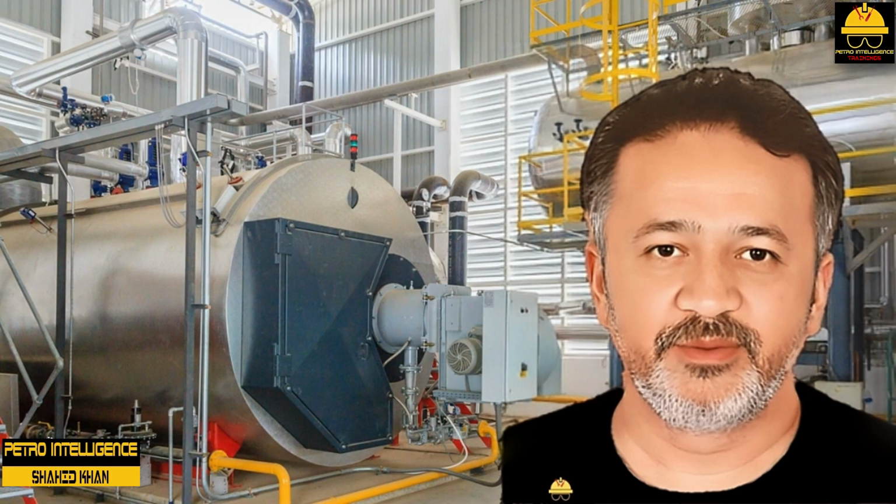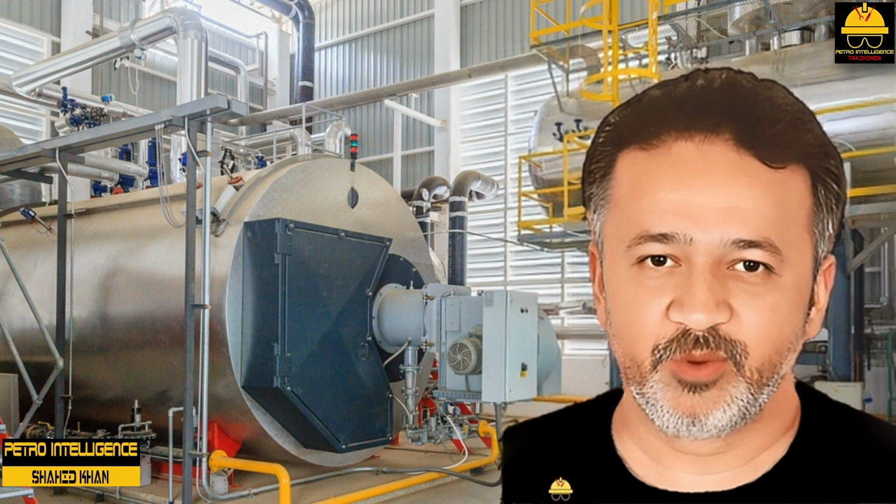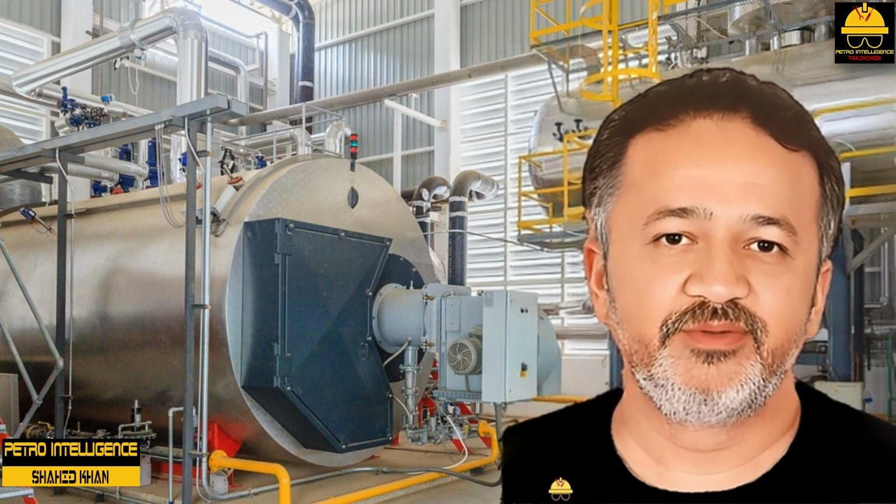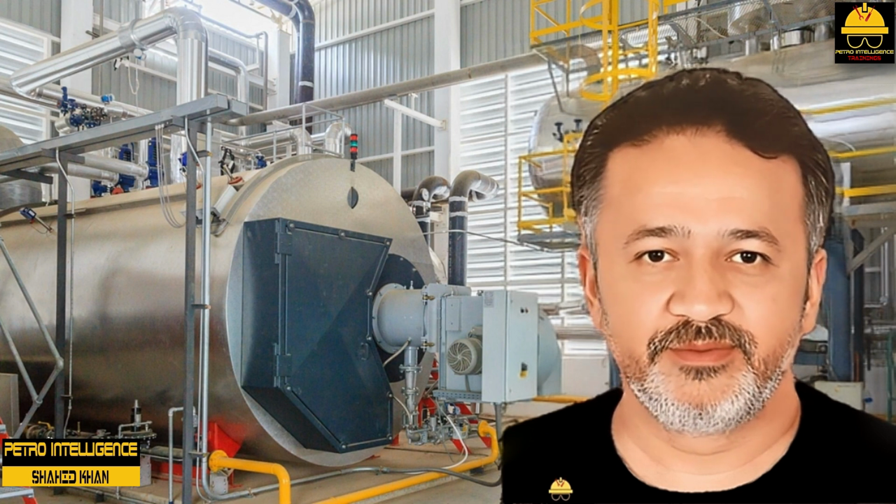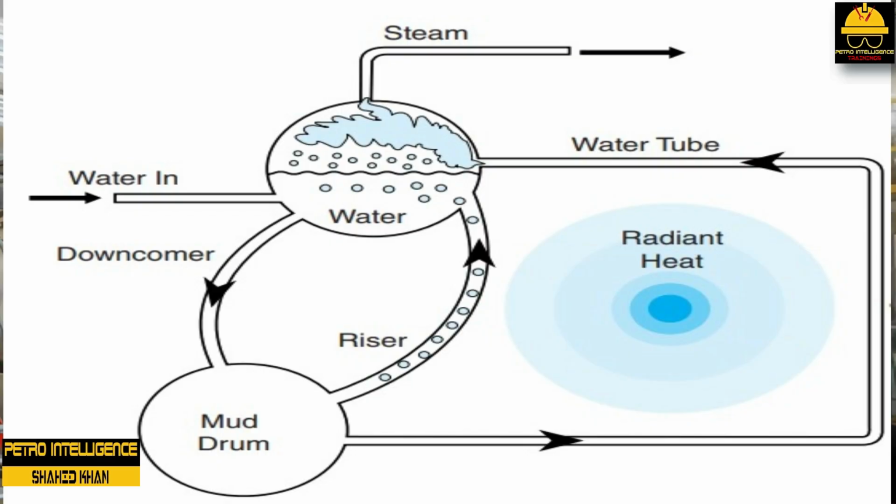We will now discuss boiler functions. When a boiler is being started up, the following process occurs. The furnace, which contains cool water in drums and tubes, starts to heat up. When the burners are lit, hot combustion gases begin to flow over the generating tubes, riser tubes, downcomer tubes, and drums. Radiant, convective, and conductive heat transfer begin to take place.